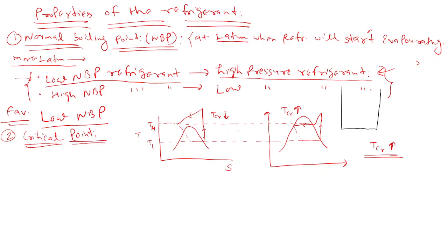No, no. Critical temperature is simply the temperature at which latent heat would be zero. In other words, latent heat zero means no two-phase region would be there. Directly liquid goes to vapor. No liquid plus vapor zone. So here, what happens if we start compressing it? It would be vapor here, and here also vapor, all vapor. So now only vapor will go to the throttling valve.